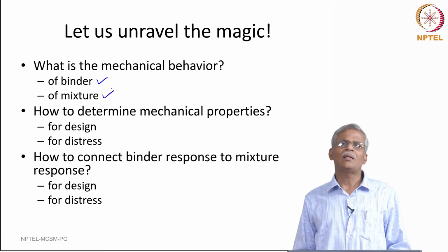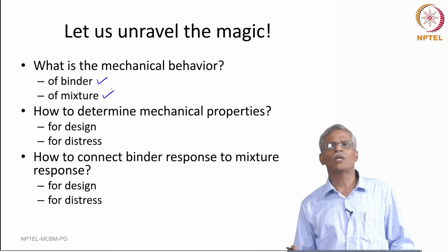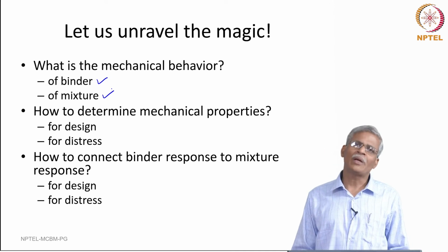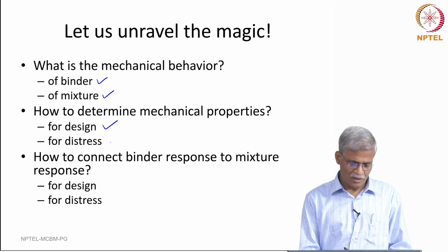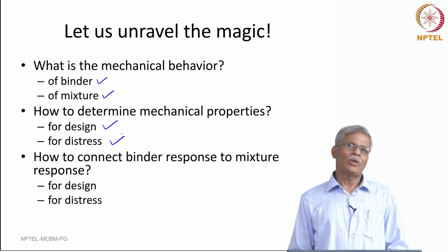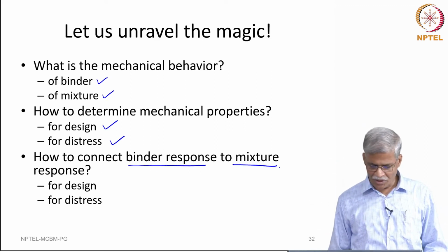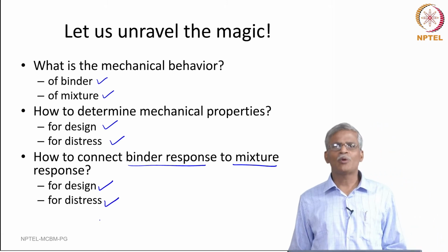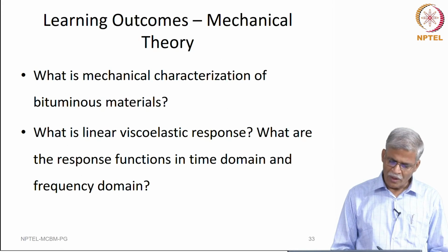Then, as we discussed in the design, when I showed you the MEPDG design framework, how to determine the mechanical properties for design, how to determine them for distress, and how we connect the binder response to the mixture response for design as well as for distress. This is the procedure that we are going to follow in this course.